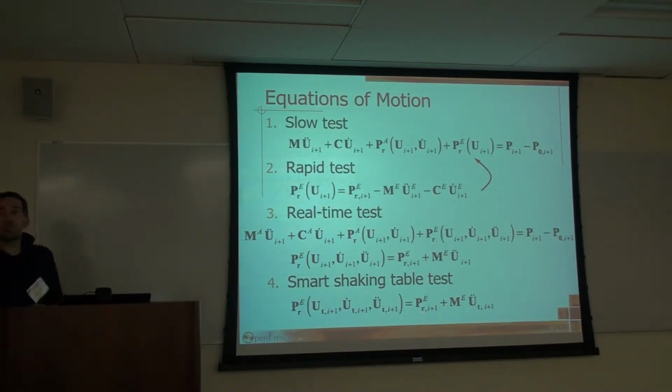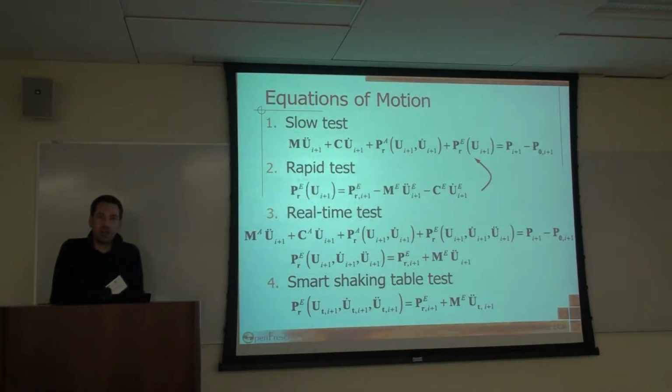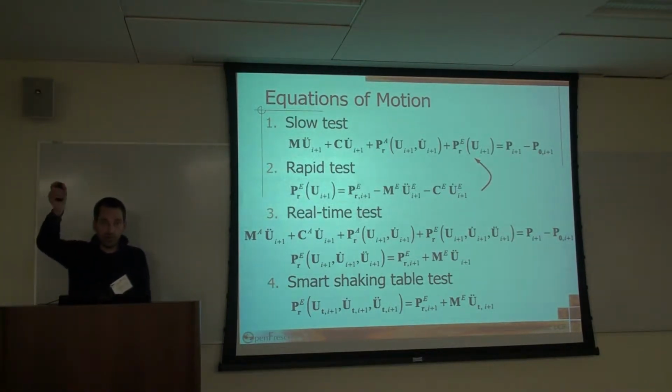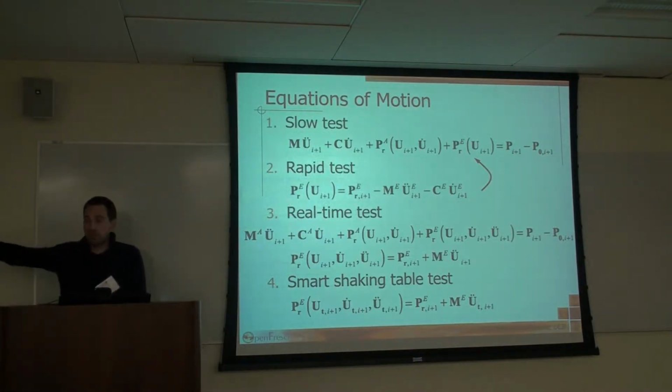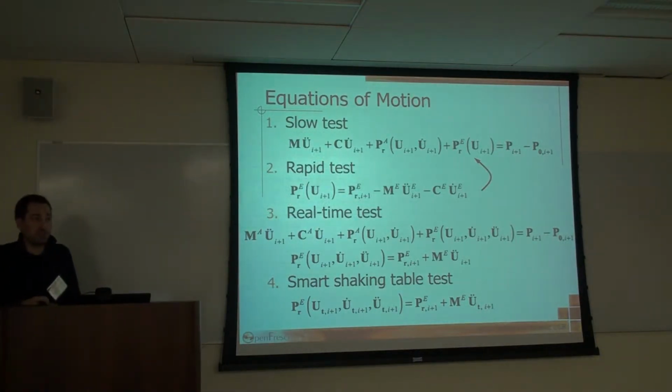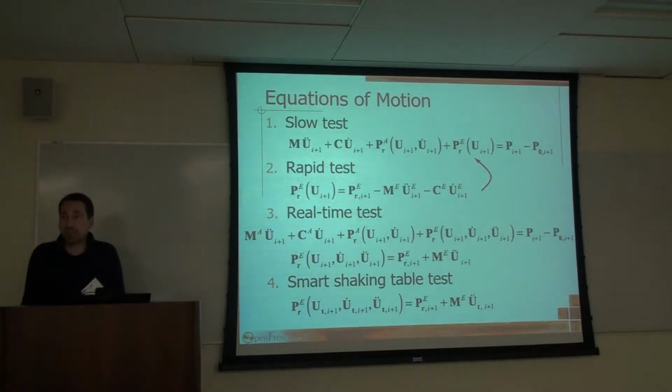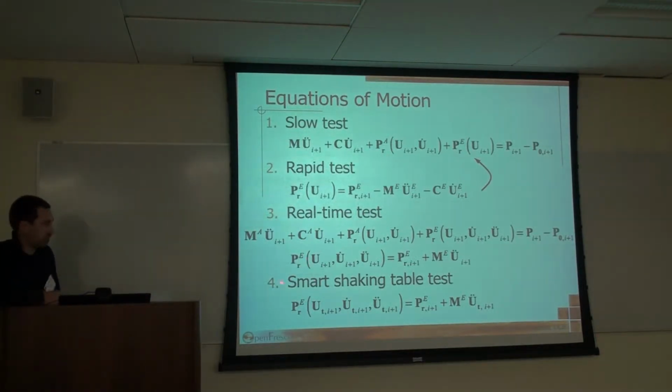The ground needs to be part of it, right? Because when we shake, if you think of the tall building application, and we want to know what the roof is doing at the interface degree of freedom, where our tuned mass damper is, what we need to send to the shake table is not relative to ground, but absolute to ground. And that's the difference there.